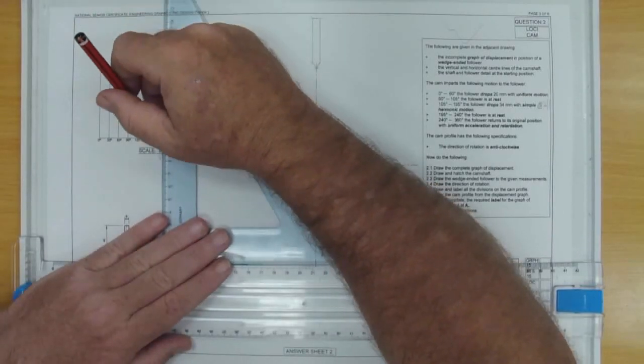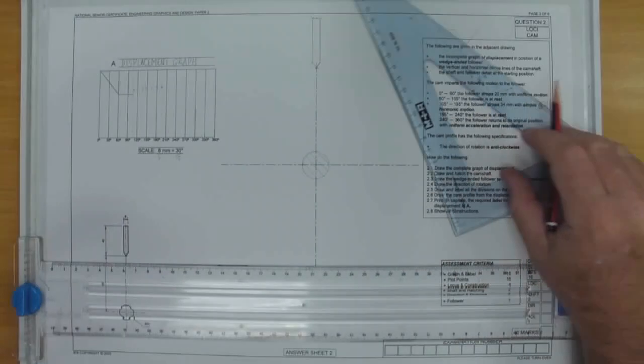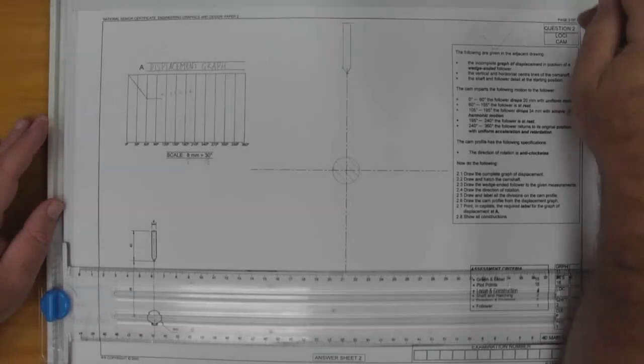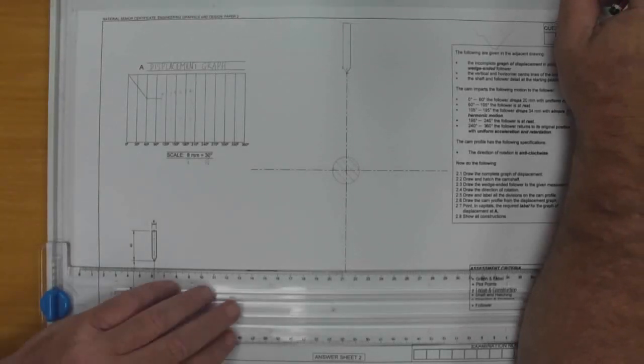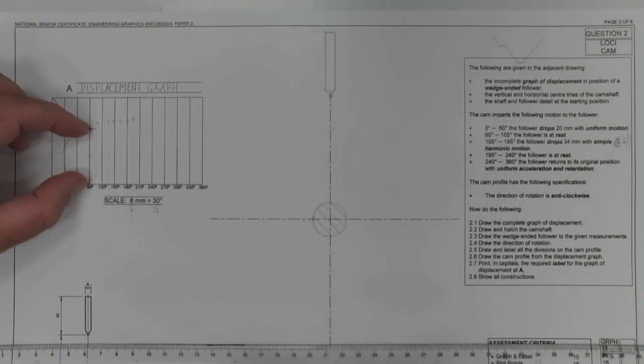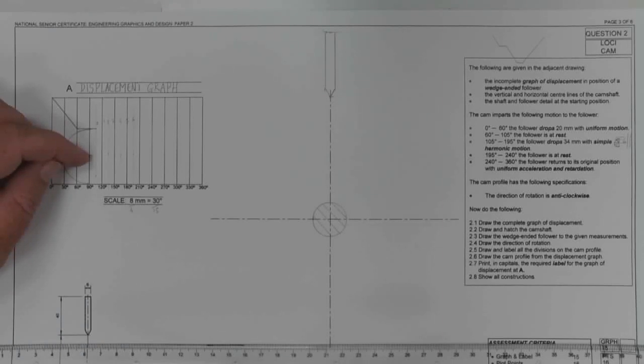Okay, this is a construction line. Hopefully your construction line is also relatively light. Now this remaining distance, when I check, is that distance of 34. So I've then just marked off 17, and I've drawn a semicircle. Again, if you've got your circle stencil, a 34 diameter circle is usually on a circle stencil, so you can use that to draw your semicircle.